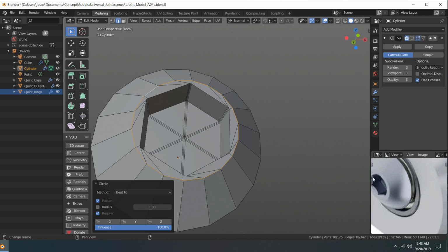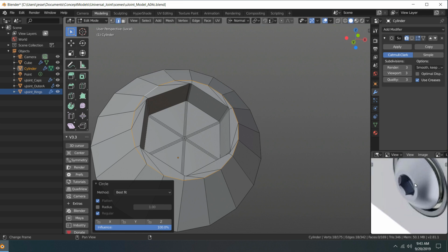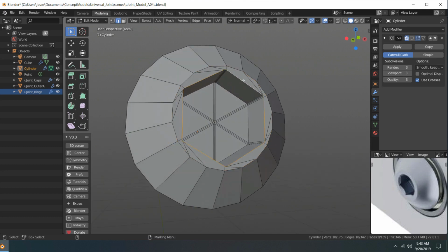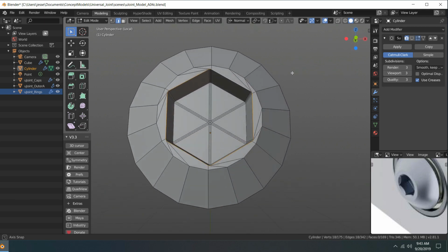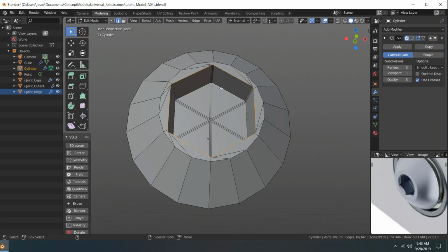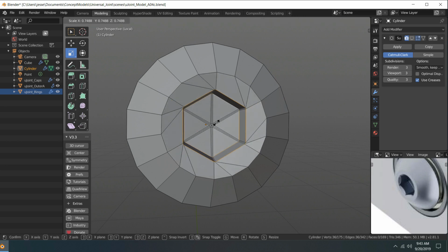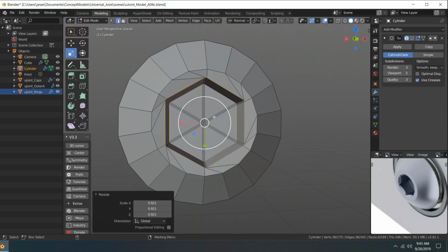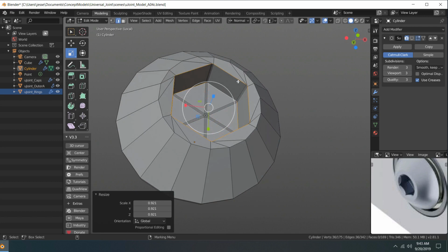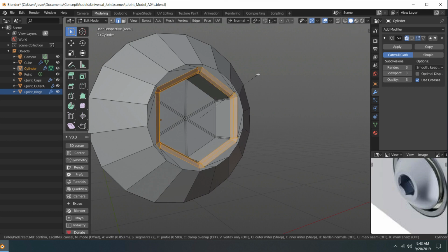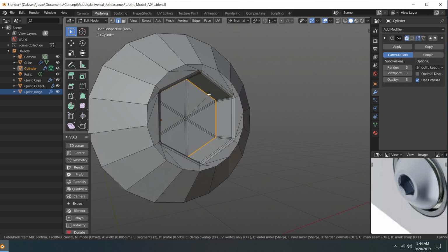So we still have got some inner detail in here. I don't know how much of that exactly we'll be able to achieve without doing a NURBS, but we'll go ahead and try here. So let's grab all these and scale in. Just a little bit there. And then that top one, we'll just hit Control B to bevel. And the same for the bottom.